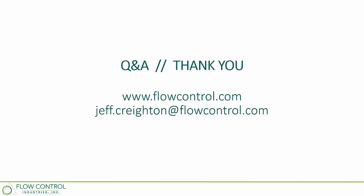A question about, do we look at the compressor energy as the entering water temperature was reduced? So we did not specifically look at that, but what we did look at was the total campus energy consumption. So that particular campus in California, the project baseline, we had an expectation of saving about 4 million kilowatt hours a year. And the measured results at the end of that project were closer to 6 million kilowatt hours, with a significant reduction in total demand as well. So even with the additional chiller consumption by providing colder entering water temperature to the coils, we still saw a much bigger impact by the total reduction in flow, and actually turning off a chiller itself was able to provide a bigger benefit in terms of the demand and the overall consumption.